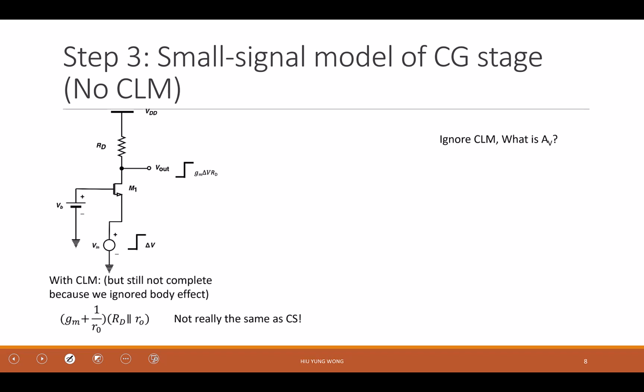Find out what's the gain of this circuit, okay? So on the left, again, this is the common gate amplifier. We have the source, we have the drain, we have the gate. And as what we said before, all we need to do first is to substitute the small signal model, GM VGS, to the circuit. Is this okay? And then we'll start computing the circuit, right?